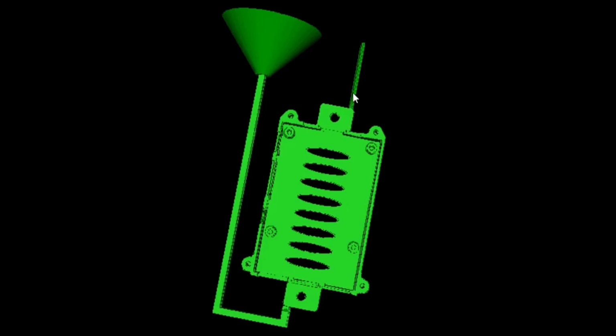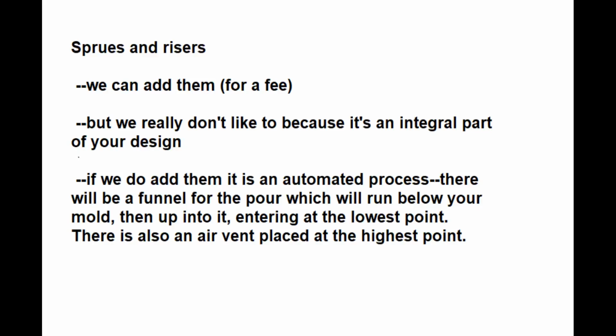Now, if you need a sprue and a riser, we can put that on for you. We will place it so that it fills from the lowest point on your model and the air vents from whatever the highest point is. But it's very important to note, we recommend that you design your own sprues and risers.